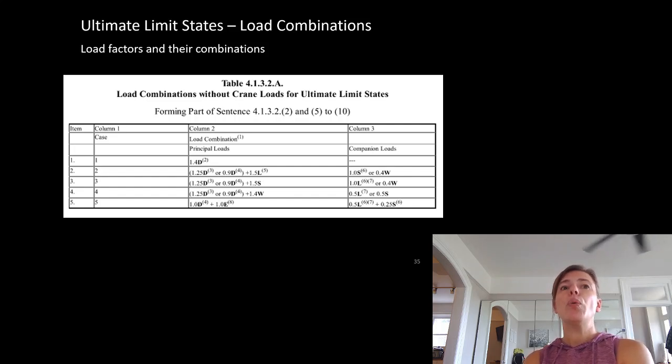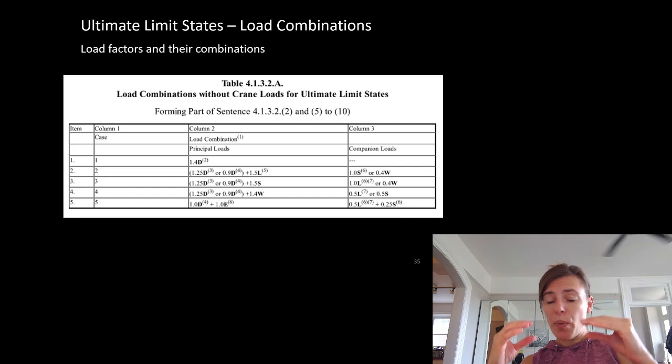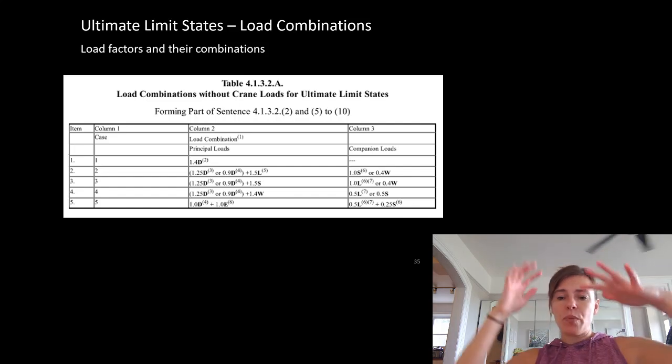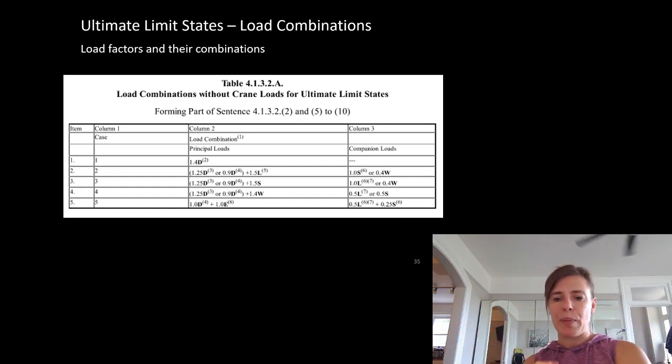We're going to talk about load combinations now. So this is how we increase those loads, or those factors we apply to the loads. Remember I said the table, we would have the thickness of it. If Shannon was standing on a table and we're designing that table for Shannon, maybe they made the table slightly the wrong thickness. Well, that's a dead load. The weight of the table is a self-weight dead load, and maybe it was a millimeter thicker than it meant to be.